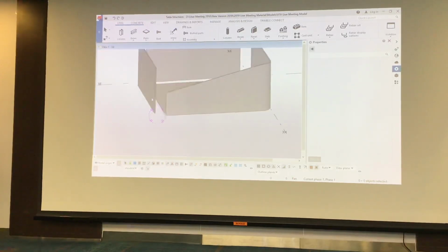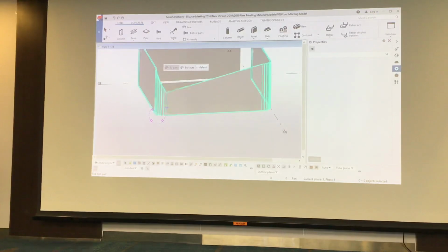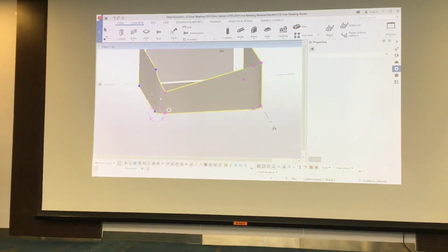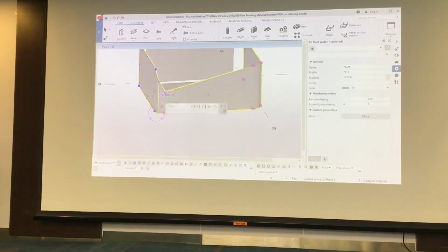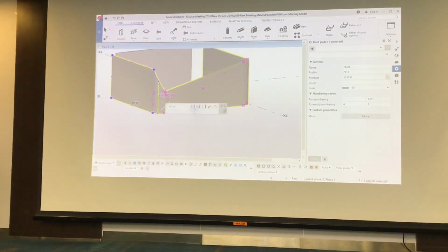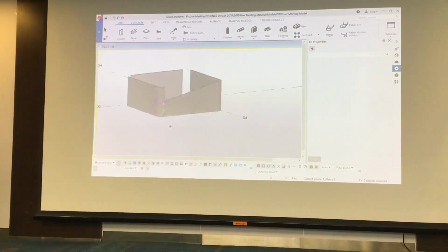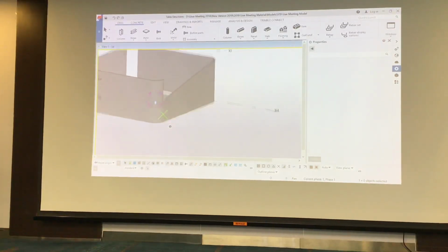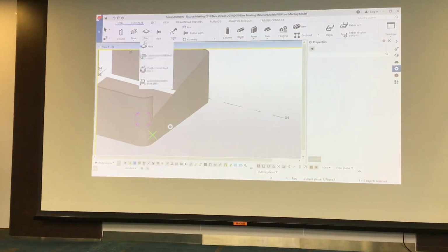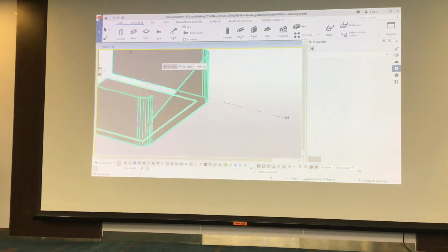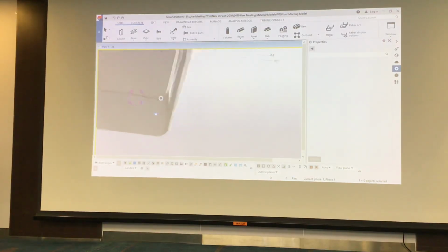If I go to this one here, which is non-size, we can say on this one, create a bent plate on those two. And also you've got the choice then, if you click on the line, you can say, look, what's the radius of that? And what type of bend is it? So you can say, look, it's straight across, it's like so, or it's merged. So you've got the choice of how the bends are like this, how you want it laid out. Right? If I click on this one here, we can say, look, repeat that from this one here to this one here, so you can join them together like this.